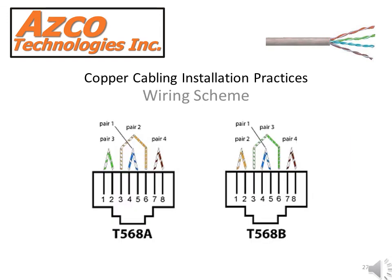Wiring scheme. T568A and T568B are two different wiring schemes. What you'll see here in the diagram, from the A to the B, is the switch of the green and the orange pairs in their spots within the pinout.